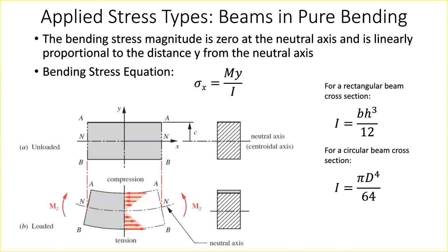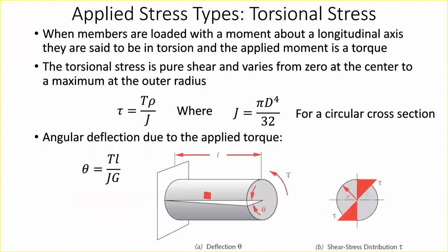If it's a tube supporting a bending moment, I can tell if that tube is large enough. Or I might realize, oh crap, my material is not strong enough, or I don't have enough space to do that. And I don't have to go through all the steps of setting up an FEA, failing the FEA, going to Kieran or someone else and saying, oh, my part failed, what do I do? It's an initial gut check, and based on that, I know how to proceed with designing the part and not waste my time on setting up FEA or something like that.